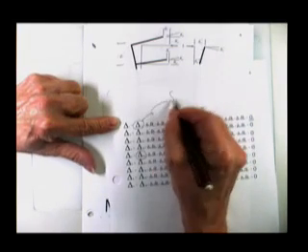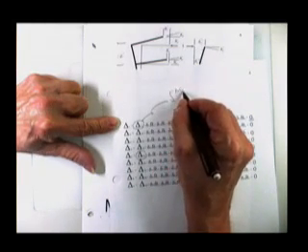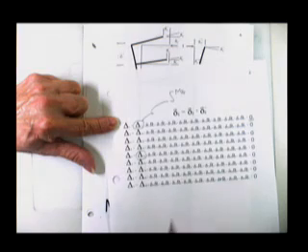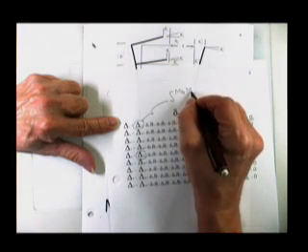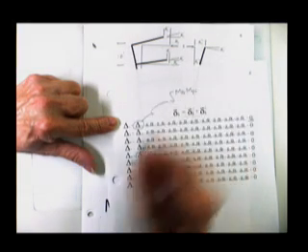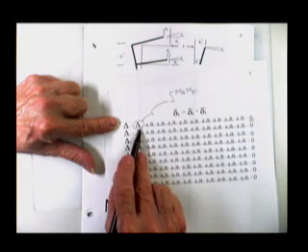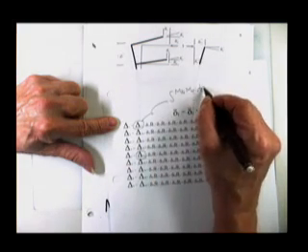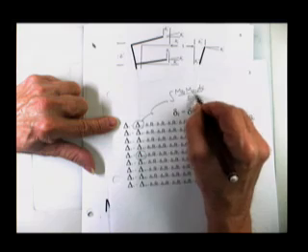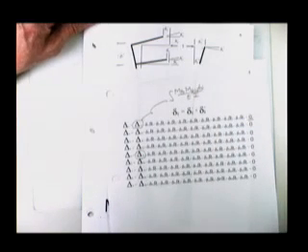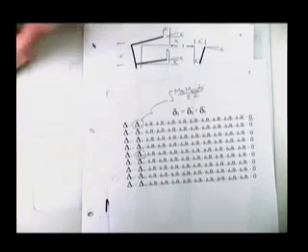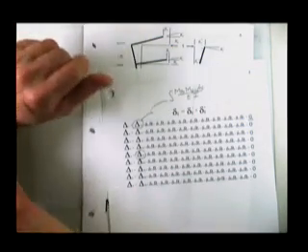That is the integral of m due to the real loads times m due to the q loads in the 1 direction. There's your 0, there's your 1, dx over EI. You can write equations for those triangles, or you can use volume integrals. But I think volume integrals are always easier, but it's up to you.